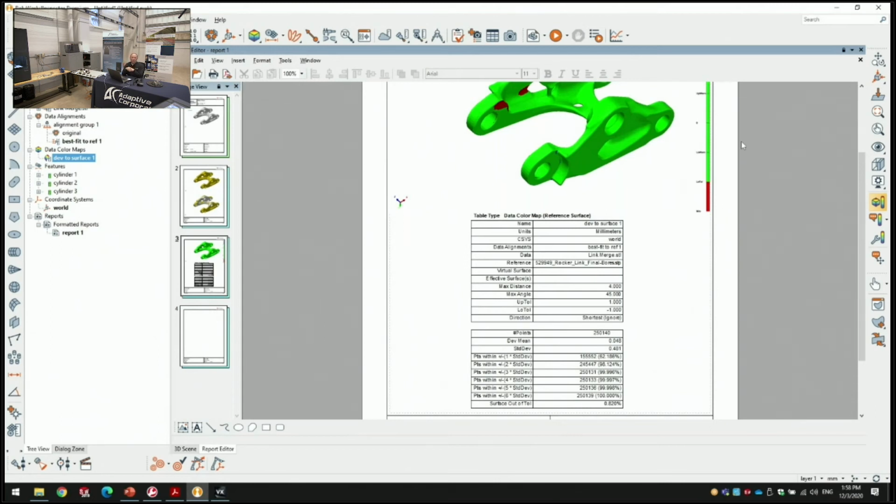We have another piece of software that we're not going to feature for you today, but it gives you the ability to create the AS9102 or the PPAP. You basically open up the PDF, and as you pick dimensions, it balloons the dimension and then creates the PPAP. So as I pick, it adds balloon, balloon, balloon, and then adds an entry for the dimension of each one of those features that I pick. So that may be something of future interest for a future webcast. The point is that inside of PolyWorks, as I scan the individual parts, I can automatically add the as measured dimensions back in to the PPAP or the AS9102 without having to manually rekey it.